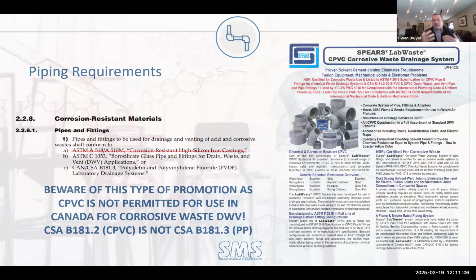So just to back up a little bit, CPVC and PVC are solvent welded systems. So they are, by nature, changed in their properties to solvent weld them together. Using a solvent, it liquefies the pipe and the fitting surfaces. That's where you get solvent welding, because the actual solvent is used to soften the material to put them together.